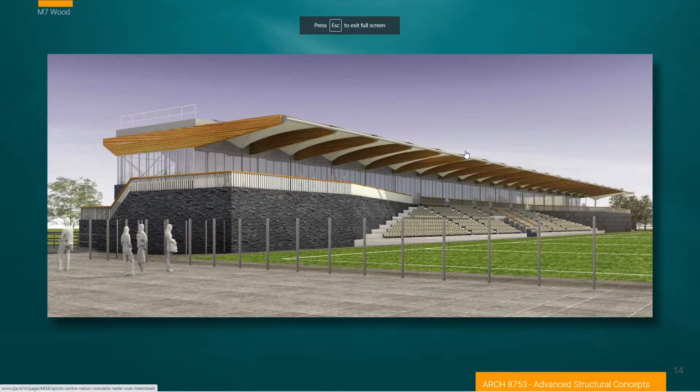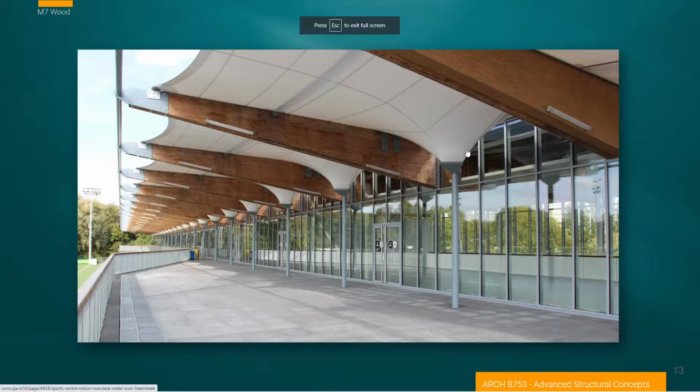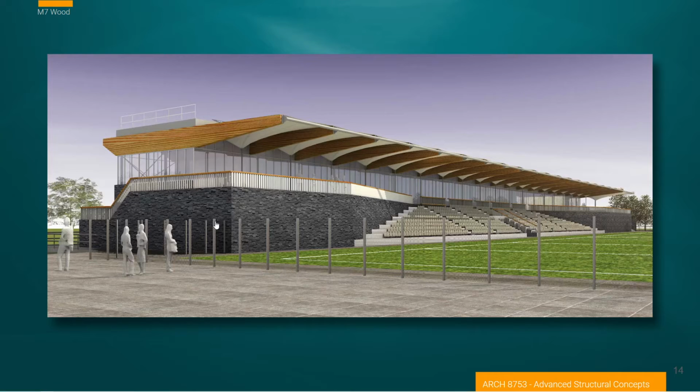But specifically on the techniques here, what I think are noteworthy are the combination of wood systems with these metal trims on them to form attachment points for what is a skin. This could be a printed ETFE. In this case, it looks like a fabric, Teflon-coated fiberglass fabric, supplied by a company like Birdair. You notice the shapes, how they're collecting water. So there's a lot of interesting ideas here that could be combined with the project we're working on this week.